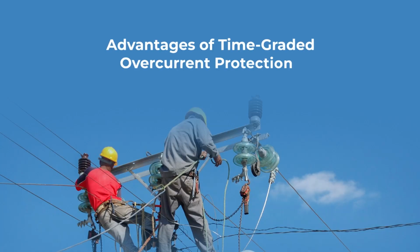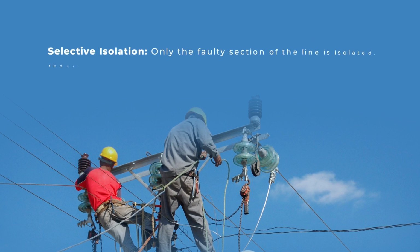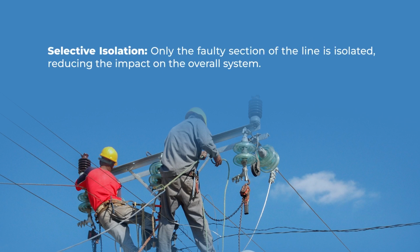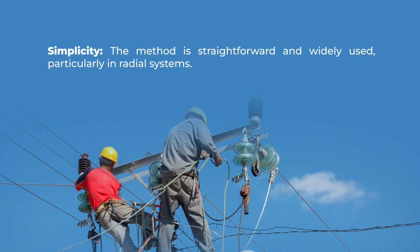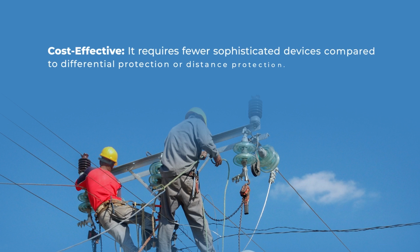So, the first advantage is selective isolation. Only the faulty section of the line is isolated, reducing the impact on the overall system. Second one is simplicity. The method is straightforward and widely used, particularly in radial systems. Next one is cost effectiveness. This method requires fewer sophisticated devices compared to differential protection or distance protection.